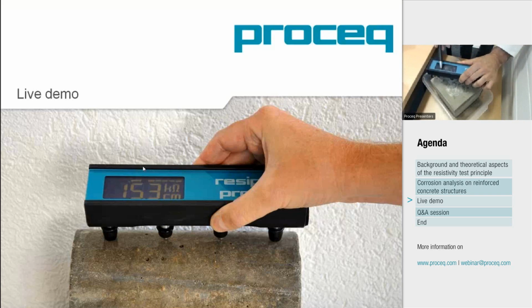Here we see our actual value of resistivity, and on the top of the monitor we have an indication of the current that flows between the outer probes. We want to make sure that contacts are good. So here we have an indication of the top of the global scale of the current, which in this case is 200 microamperes, and it could be a lower range for lower resistivity.